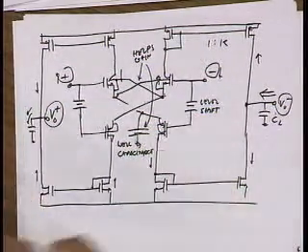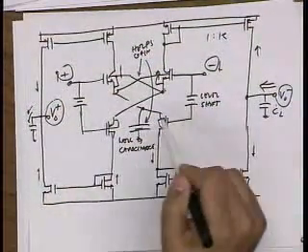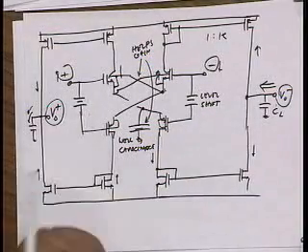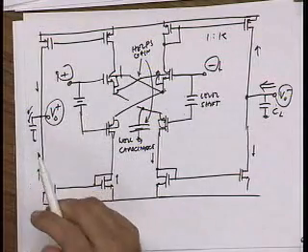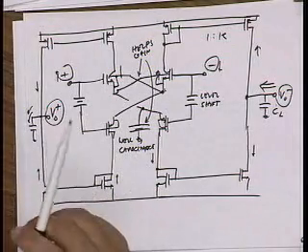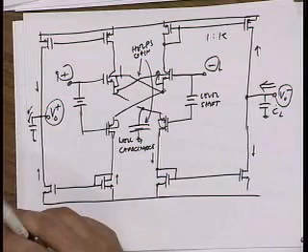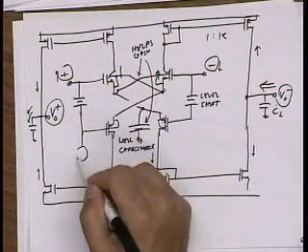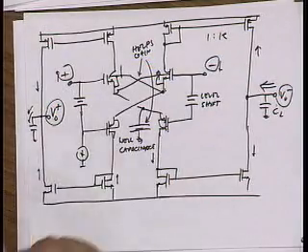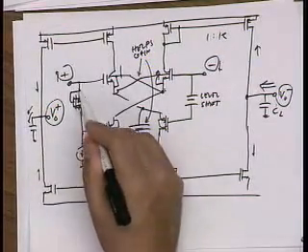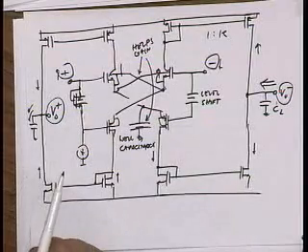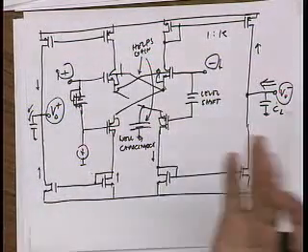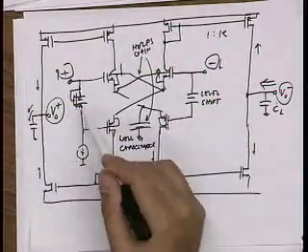The other issue is these level shifters. They seem innocuous, right? They're just little batteries here. But what's the problem with a real level shifter? Yeah, it adds power. With a real diode, I have to add a current source here, right? What else? Is it going to dump noise into your input? Yeah, noise. This is going to be noisy.